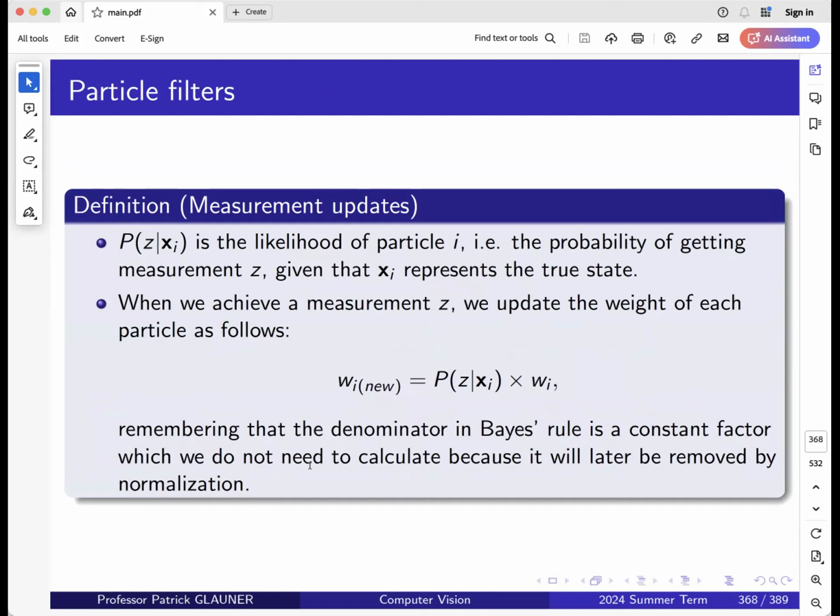You can use 2 cameras for depth estimation. If your robot only has 1, you could mount 1 more camera on top. Some students have done this in the past. However, you could also use a deep neural network, and a trained deep neural network can also allow you to do depth estimation just from single images, given that the neural network was trained on a sufficiently large training set. And I told you for the training set, we actually have a label per pixel, which represents the depth, so the distance. And then you could also predict something like this,